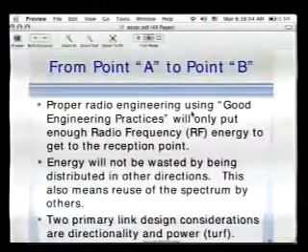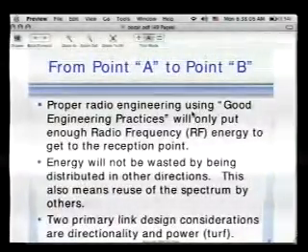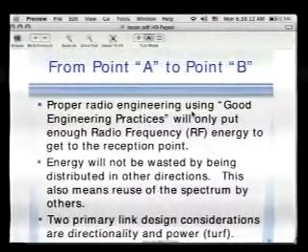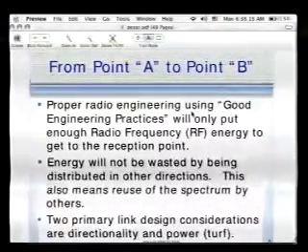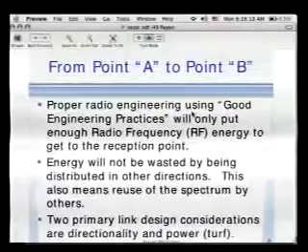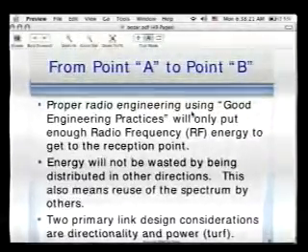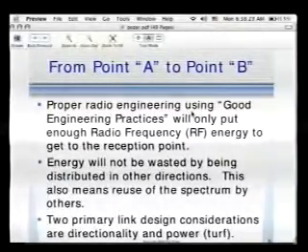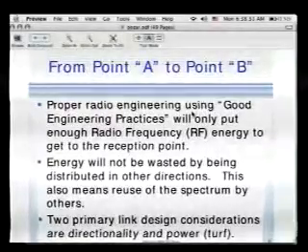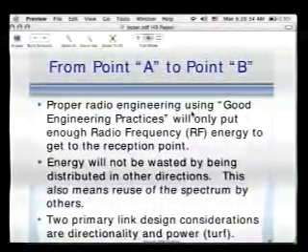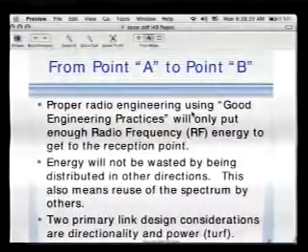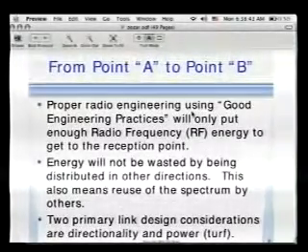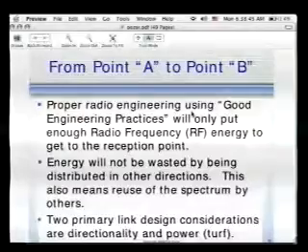So let's get a little bit more into it. That's sort of the why we're doing this. I want to talk a little bit about good engineering practices for RF deployment. Basically, from point A to point B is what you're trying to do. You're trying to get a radio signal from one point to another. Proper radio engineering, using good engineering practices, will only put enough radio frequency energy to get to the reception point. It's not going to go anywhere else. If I want to talk to that person way over there, I'm just going to send the RF energy over there at sufficient power so he or she can receive it. I'm not going to send it out over there because that'll start interfering with that person over there who may be trying to talk to somebody else.